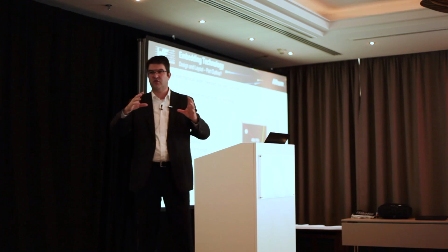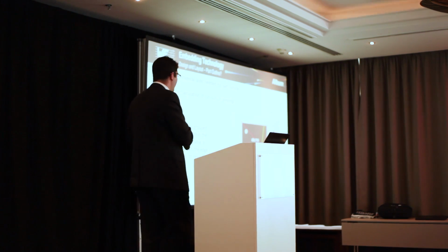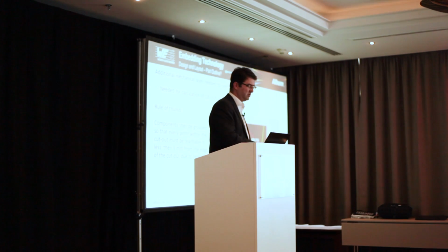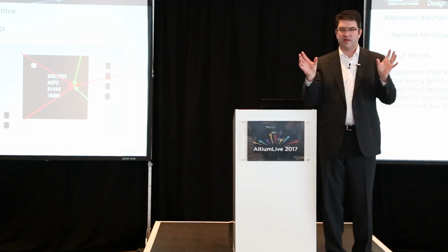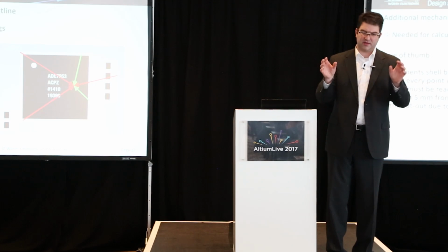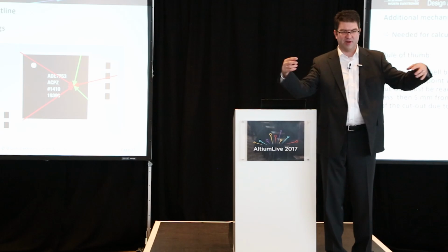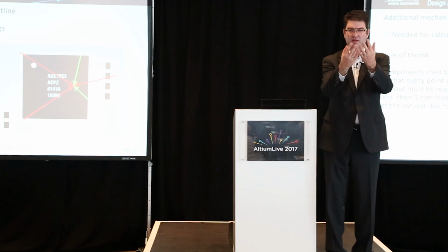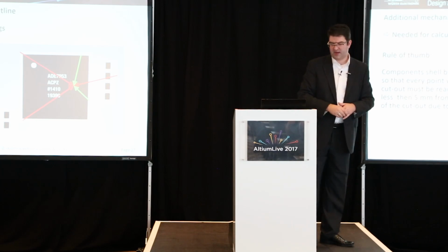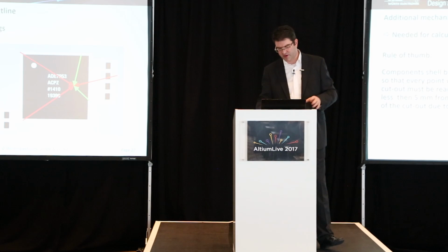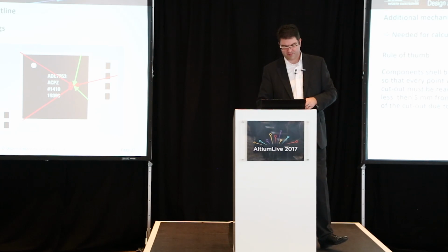So you cannot make a 2 by 2 centimeter cutout. There are maybe some ways to overcome this rule, but this is when it really gets into detail. In a multi-layer stack-up, we can make something almost like venting holes. So you can make holes into a core so that prepreg can come from the backside as well. But this is when it's getting really tight and really complicated in the calculation of the resin. From a starting point of view, it's easier to calculate what is coming from the side to the inner layer.